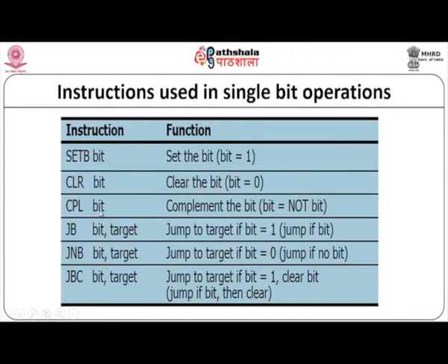So, if I give CPL P3.1, what it does is change that particular bit from 1 to 0 or 0 to 1. These are all bit operations done through this kind of command. Then JB, these are all operations.